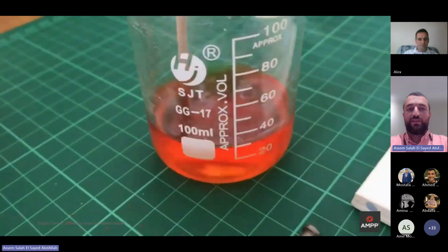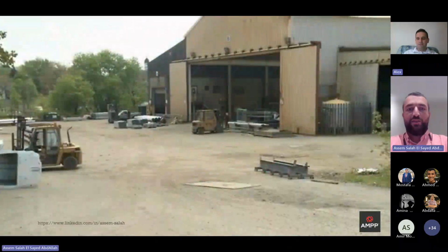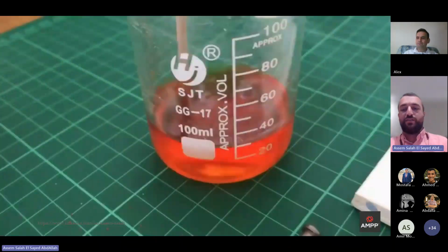And now you will cut the link between zinc and the steel bolt. And as you can see, after cutting the link between zinc and steel, the bolt will be corroded also, and will be chemically reacted. And this experiment shows you the idea of sacrificial paints. And I want to hear from Mr. Alex.